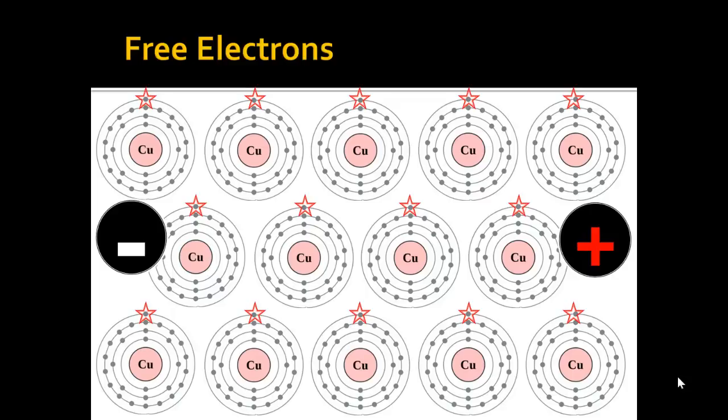So on the left end of this copper conductor, you have a negative charge, a negative ion, a negative force, which is attracting the protons in all of these copper atoms. Well, the copper is a solid. Those nucleuses are not going to move. This negative charge on the left side is also repelling all the electrons in this conductor over towards the right. Over on the right, you have a positive charge that's repelling all the nucleuses back towards the left, but again, it's a solid, they're not going to move. That positive charge over there is also attracting all of those free electrons. So on the left side, you have an excess of electrons, which are repelling all of those free electrons towards the right, and over on the right, you have a positive charge that's pulling them that way.